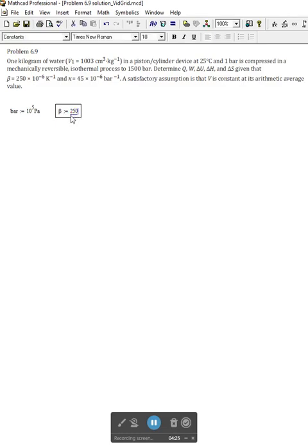So that's 250 times 10 superscript to the minus 6, and then I press a space bar to select the entire value, and then I can type in times and then 1 over Kelvin. The base unit is Kelvin for MathCAD. And so I'm just going to drag some things over that I already had typed out on another page. So there's our value for kappa.